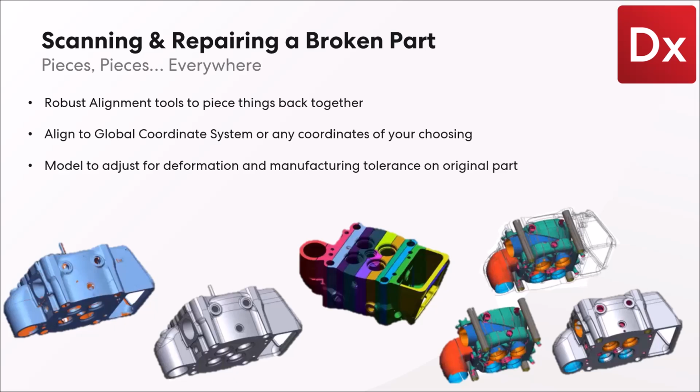How we aligned all that back together is we referenced all of these slices back to the exterior scan data of the part. We also know the kerf of the slices, so that's another thing we can use for verification. Between the deviation analysis on the scans and the kerf spacing that we have on the planes in between each other, we can check to make sure things are lined up where they need to be.